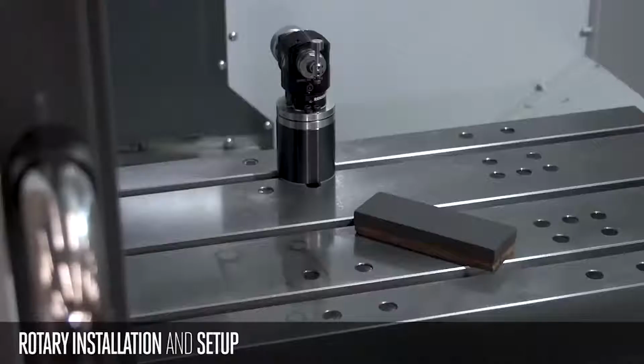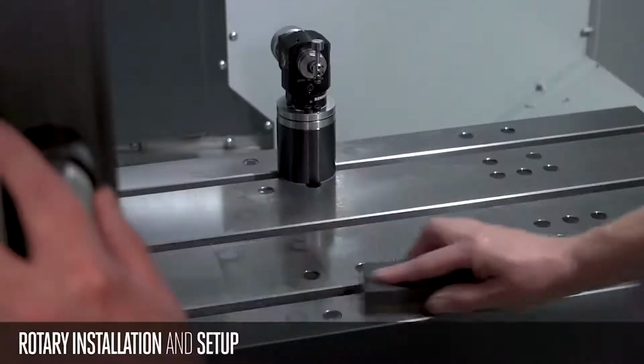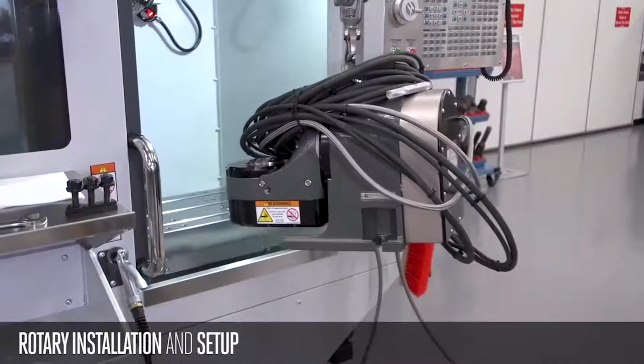All right, now let's get to the fun stuff. Time to install the rotary. I'm going to stone the table and make sure I don't have any high spots, and then spray it down with some rust preventative oil, and we should be ready to go.